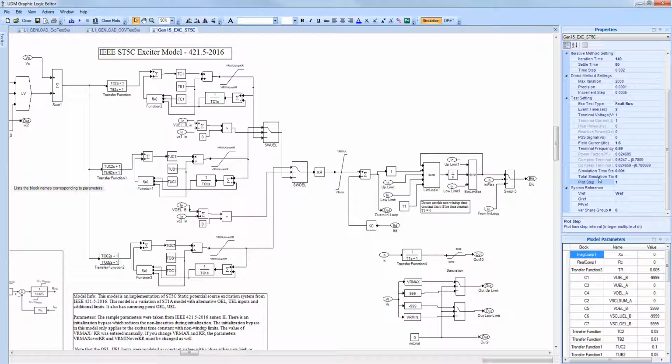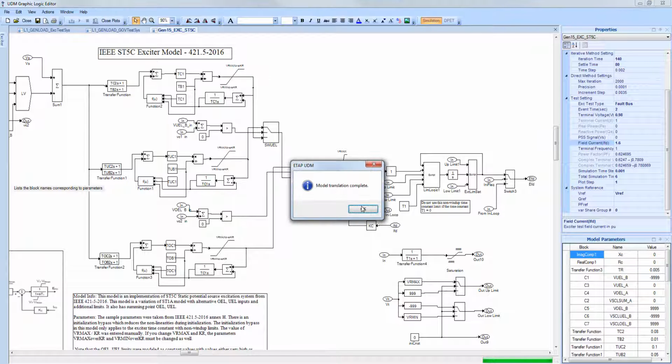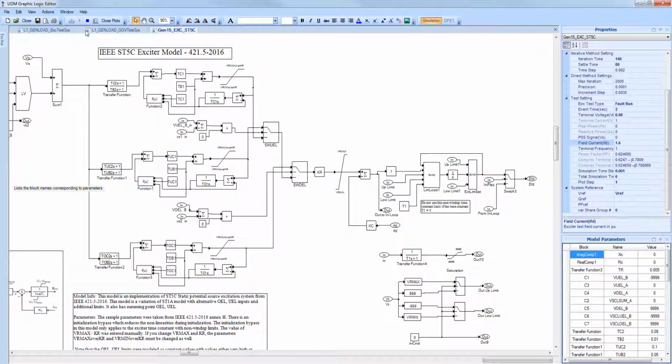In this case, we could define the initial voltage at the output bus of the generator, so that the exciter will regulate the voltage to that desired value upon initialization. And we could also define items like the input frequency, which is an external parameter fed into the generator. Making those changes allows us to define the initial conditions in better fashion to complete our tests during the simulations.